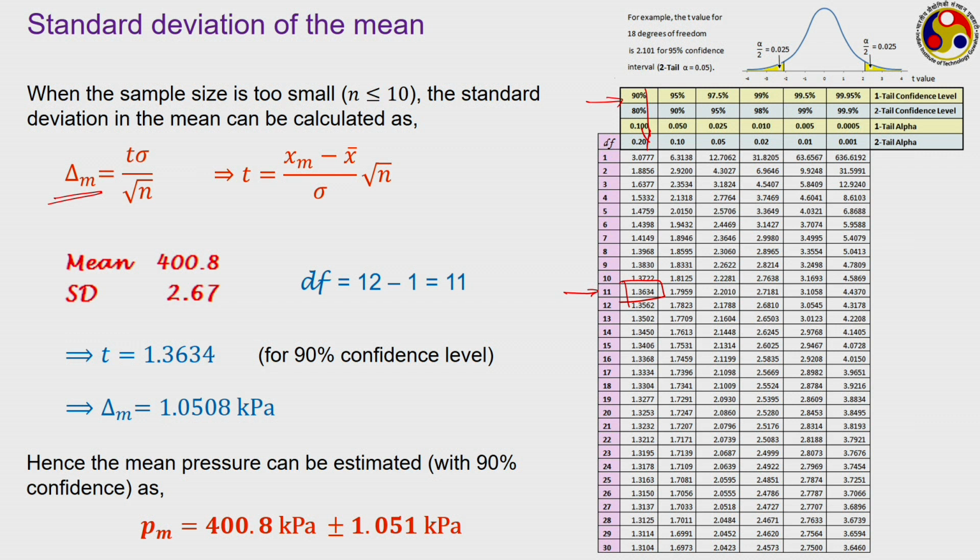we know the mean, then we can go for the recalibration process to identify the standard bias present there. This all is related to the randomness or precision error that can be present in the measurement, and this mean itself is associated with the standard bias. So, in a sampling process following the T test, we can also identify the error that can be present in this mean itself.